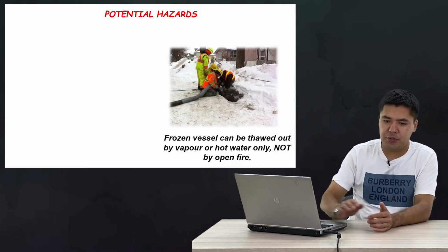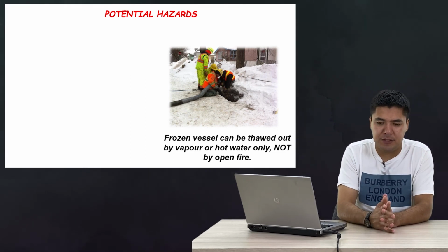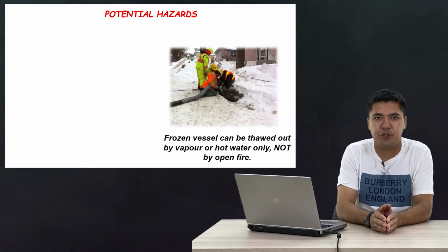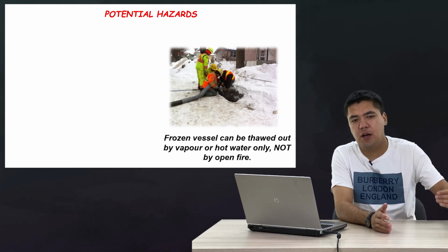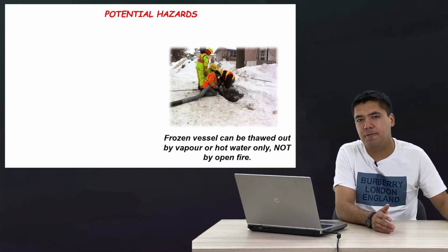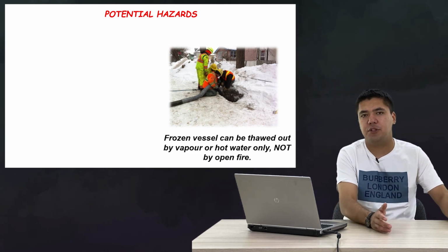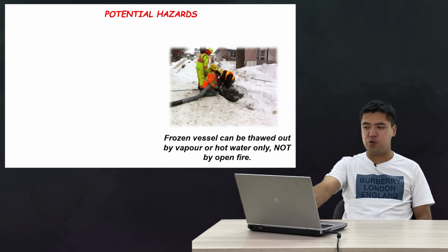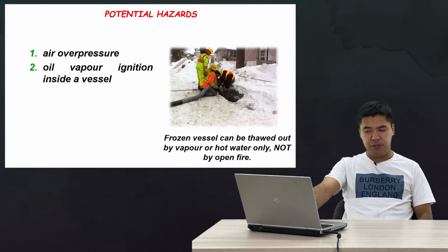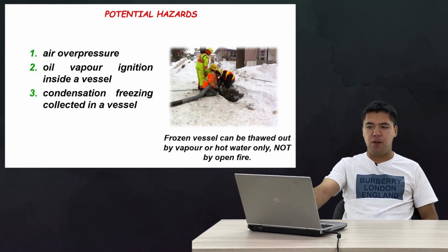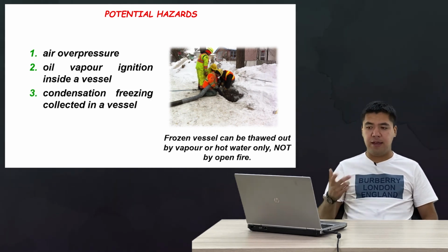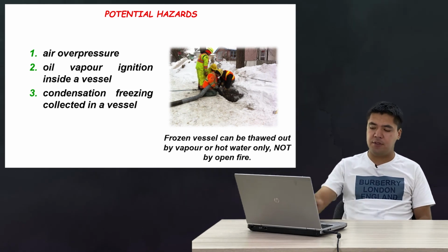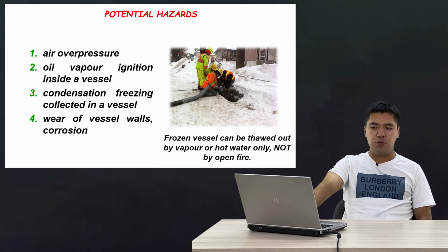And next, I would like to highlight the basic hazardous moments for operational personnel who work with pressure vessels, who every day face different hazardous aspects while working with pressure vessels. The first hazard: a frozen vessel can be thawed out by vapor or hot water, not by open fire. Potential hazards: air overpressure, oil vapor, ignition, condensation, freezing collected in a vessel, and wear of vessel walls, corrosion.